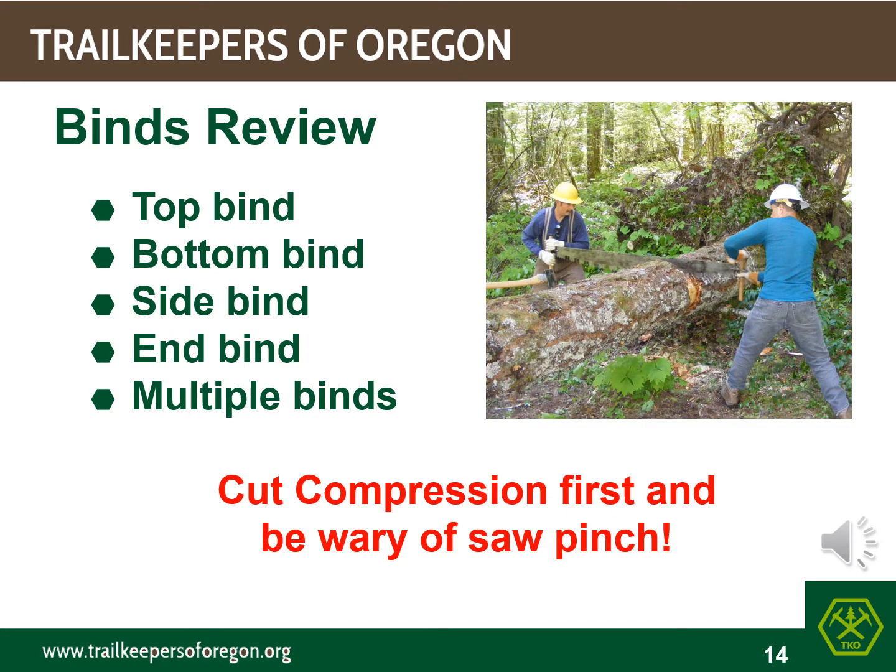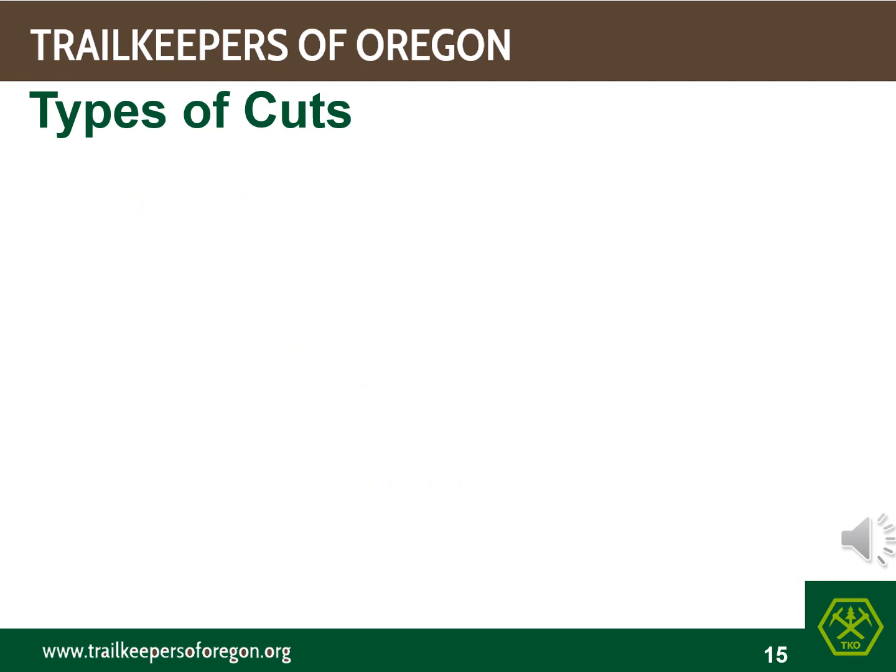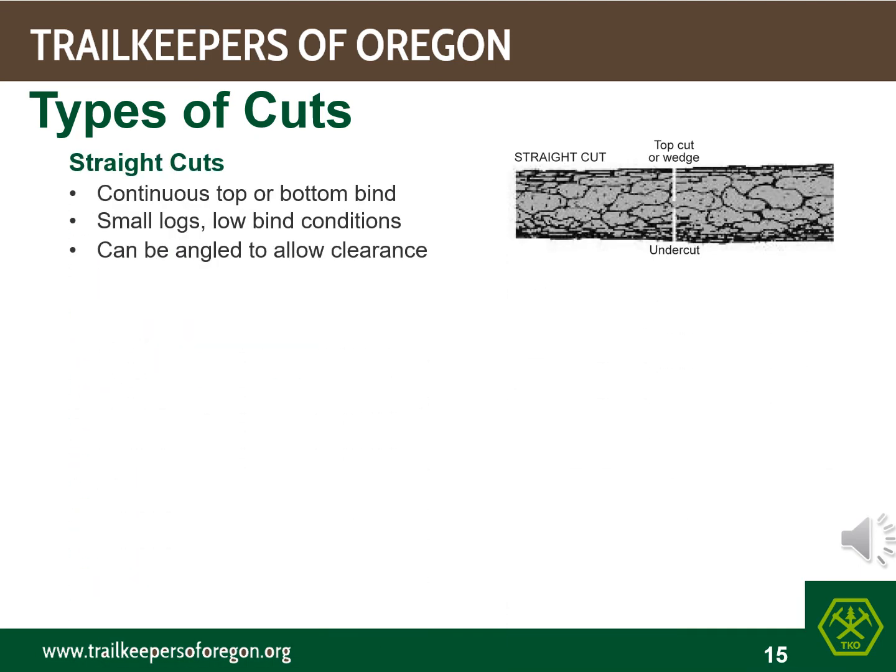Now we're going to discuss a bit about the types of saw cuts you can make in a log. These are the more common types of cuts the sawyer team will use. Straight cuts are perpendicular to the length of the log. They are a very common cut for most log situations.